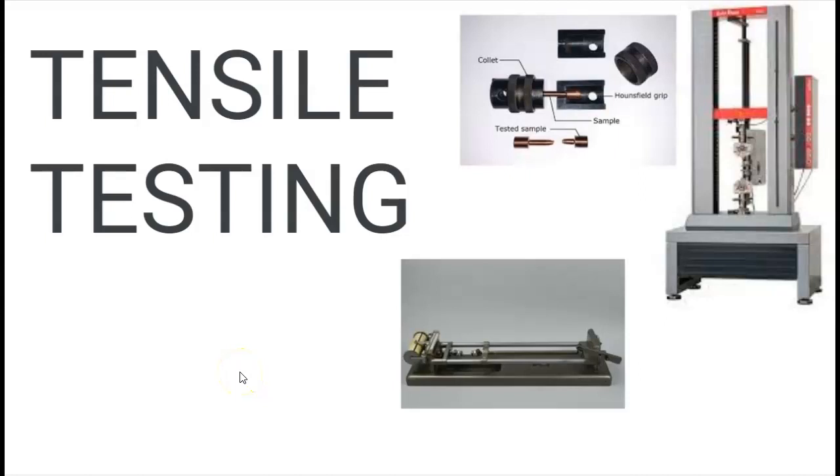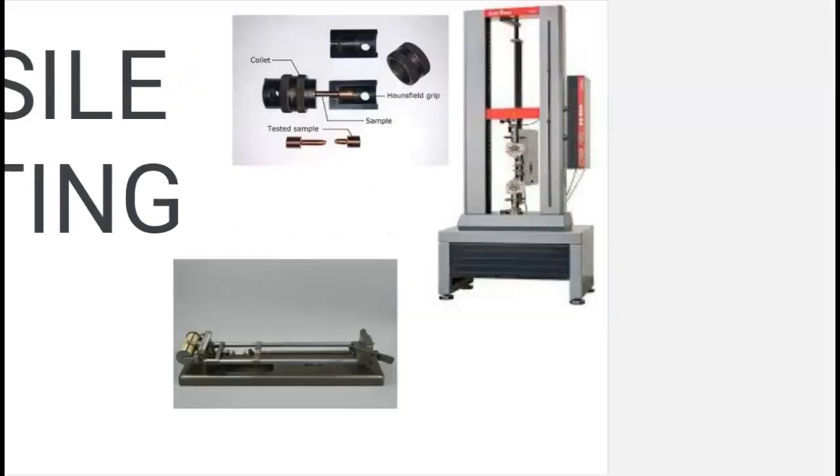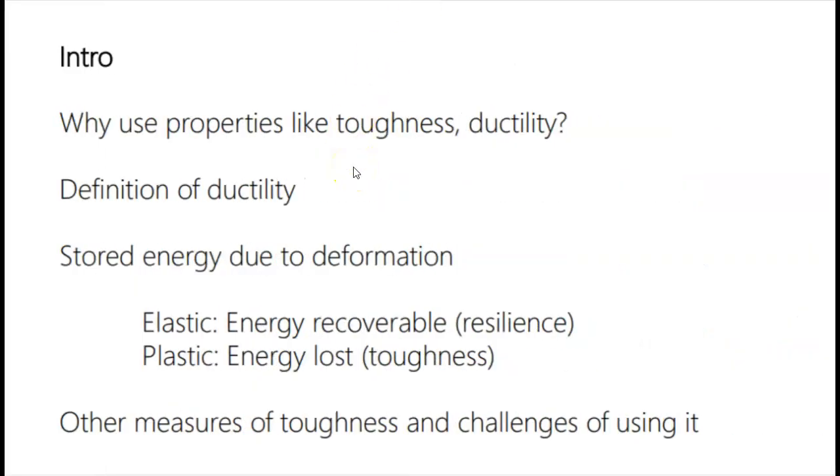Okay, let's have a look at the tensile testing of different materials. Now, why do we need to do the tensile testing? We need to find the properties of the material to make sure we know the failure point, the failure stress, the yield stress, and the yield point, so we can work within the factor of safety. We can also find out the elastic energy and the plastic energy absorbed by the materials.